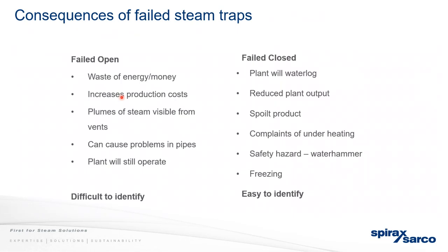Complaints of underheating, so again, as we just said, safety hazard, water hammer. So if you have this slug of water hitting down onto closed valves or traps, you can have a failure, and when they fail, they can crack. So if you take a cast iron trap, for instance, you could introduce microfracturing, and at some stage that trap will split open. And freezing again. So if it's a cooler trap and you have the conditions available, it's more likely to freeze.